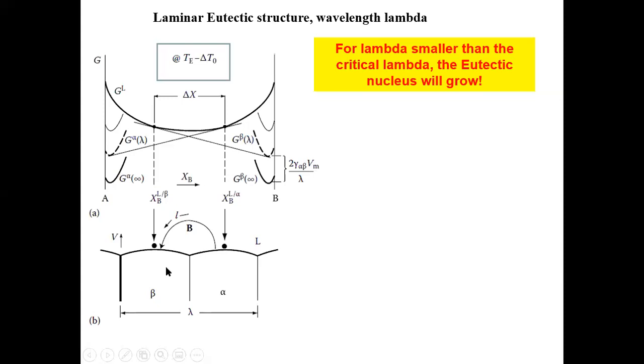So now basically, as we already said before, far away from the solidification front, the liquid is going to have the equilibrium composition, which is the eutectic composition. But near the solidification front, in order for the solid to really grow, for the alpha phase, we know this is A rich, right? So it wants to repel as many B atoms as possible.